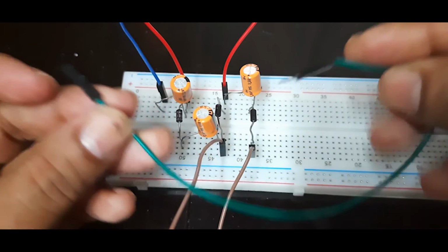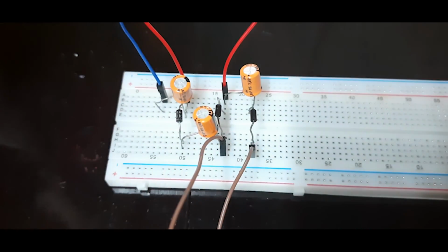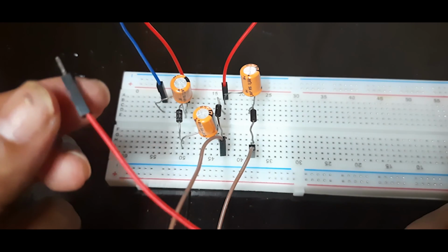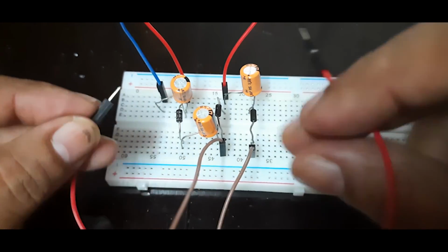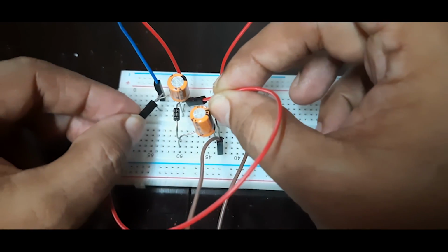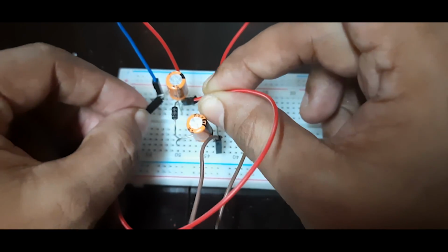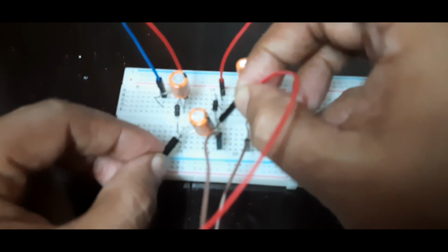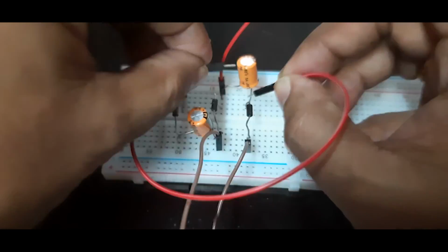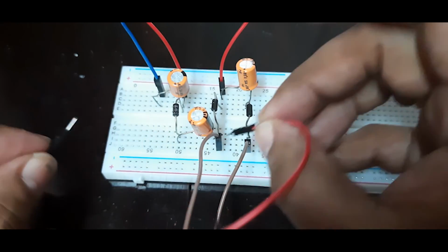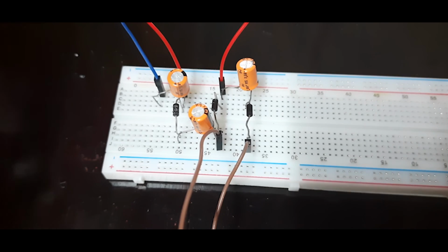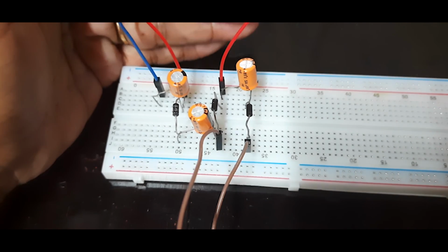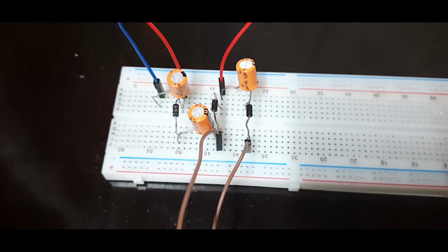I've taken a small wire. Sorry, I'll take another one. I've taken a wire. Two ends of this wire are male leads. So just touch the two ends of the capacitor, two terminals of the capacitor, like this. If you had noticed, you could have seen a small spark that came here. So make sure that you disconnect this from the input supply and then do the shorting.